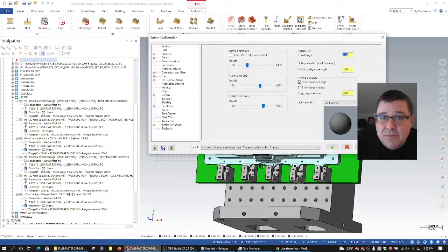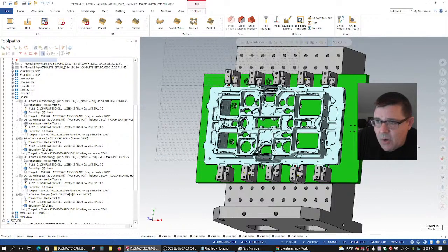thousandths. So kind of half a millimeter, quarter to a half a millimeter, I guess. In this case, 20 to 40 thousandths for my chord height. And if you do that, so I'll do that and set my chord height to be pretty loose like that. So I'll select OK.